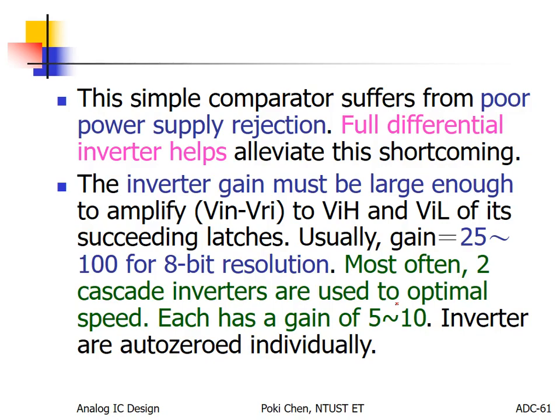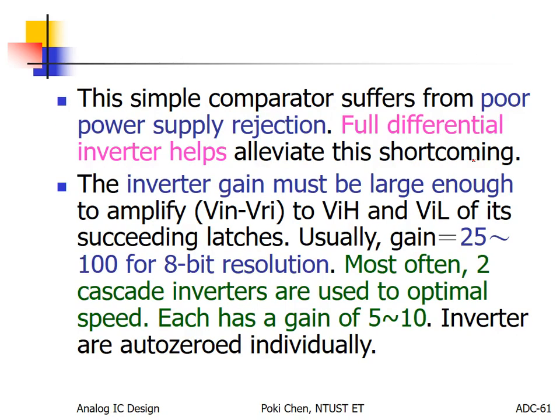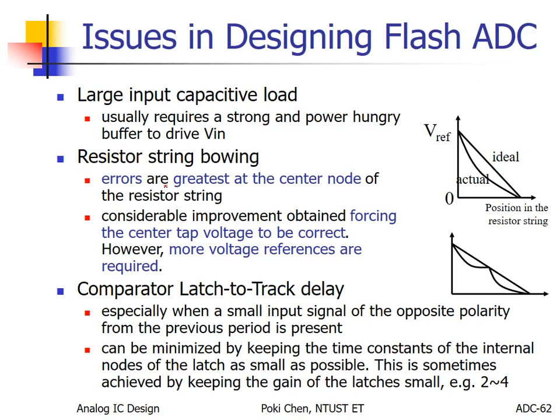But that is only single-ended operation, right? Usually, we need a full differential inverter. And then, for the design of such kind of flash ADC, for INL, usually it looks like this. Not exactly, but where will be the maximum INL error? Usually in the middle.